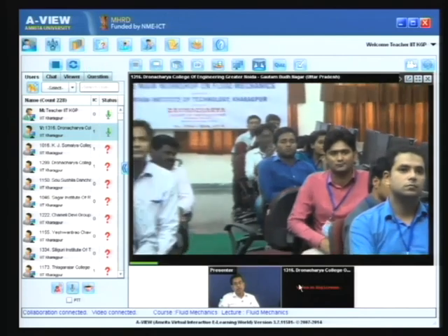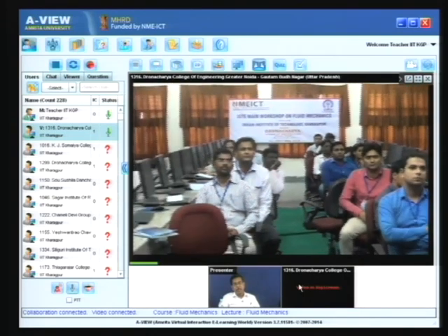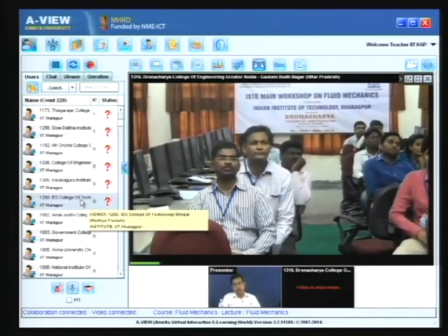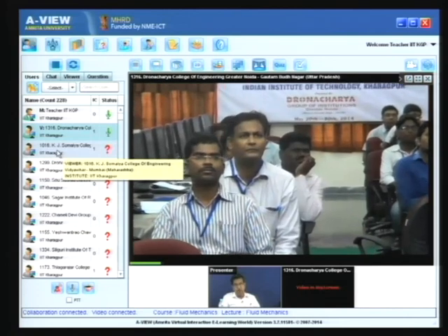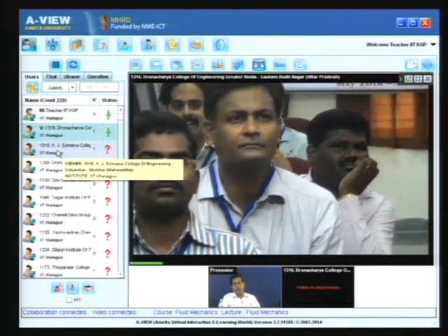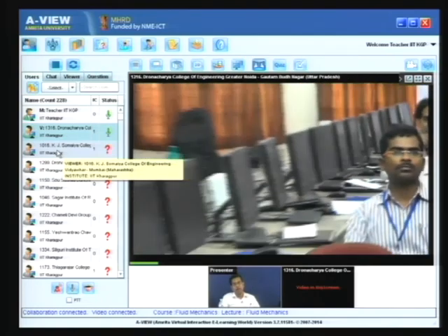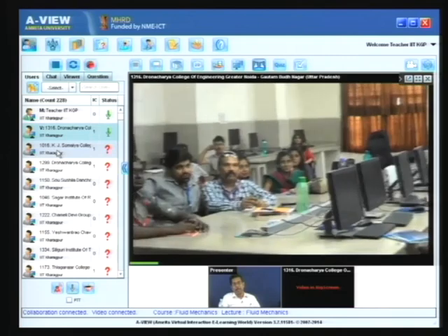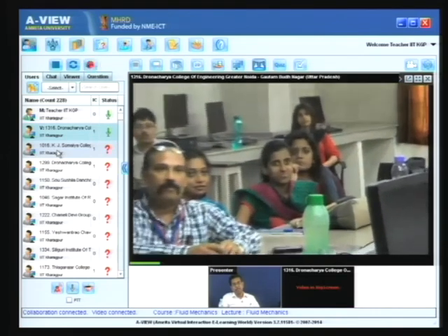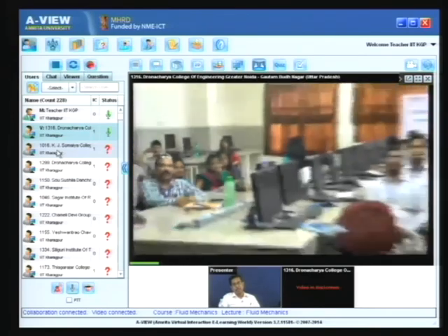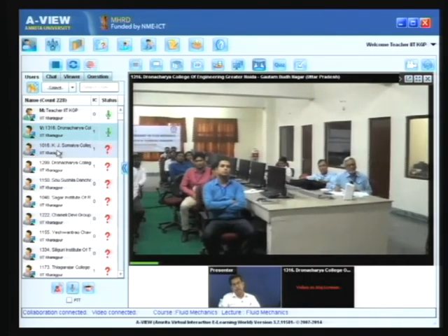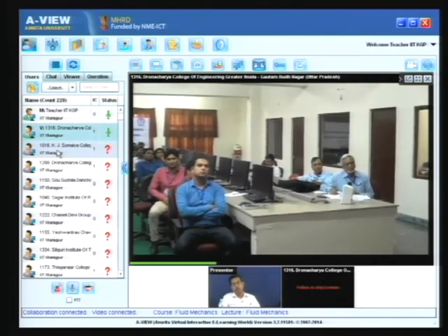Yes, it is a good question, I appreciate it. To find out the dimensionless numbers governing a particular problem by applying either Buckingham's pi theorem or Rayleigh's indicial method, you have to identify the physical parameters, and that has to be done from knowledge of the physics of the problem. There is no formula for identifying them. For example, a fully developed pipe flow is governed by viscosity, density, the reference velocity, average or uniform velocity, and the diameter of the pipe. So, all these things have to be known clearly.